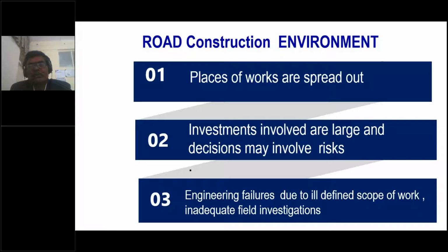the detailed project report based on some sample tests. Let's say generally we take one soil sample at every 1 kilometer, and we presume that the entire 1 kilometer is represented by the properties we determine from that one specimen we take in each 1 kilometer.